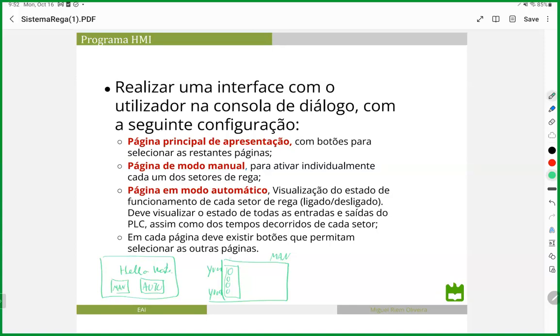So this is just a monitoring part of the system. And here you should have some buttons for pressing and for turning on. For example, here is turn on YV01. If I press here, YV01 should be activated. Again, this is some control logic that perhaps should be in manual mode or not. We'll get it.